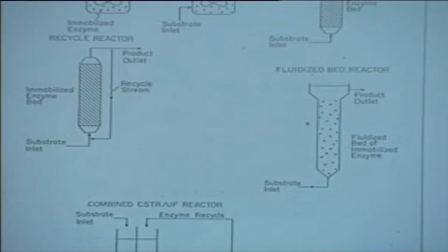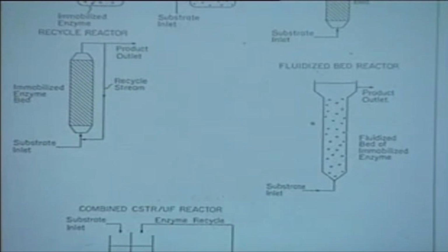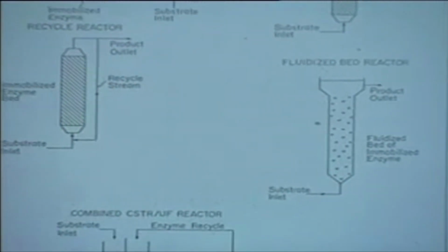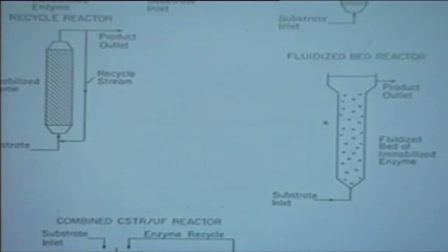It can act as a batch immobilized enzyme reactor, a packed bed with total recycle. The only constraint or assumption to be considered, from the quantitative point of view, for treating it as a perfectly mixed batch reactor is that the recycle time of the substrate must be very small compared to the total batch time.